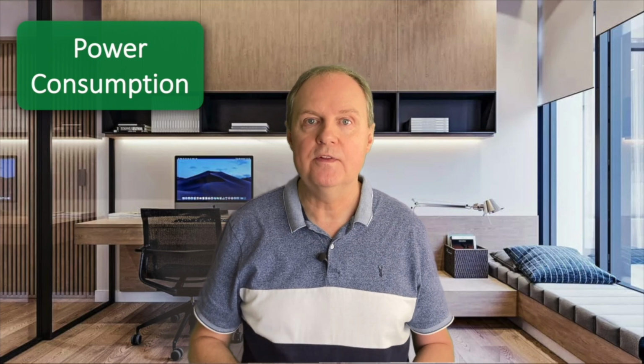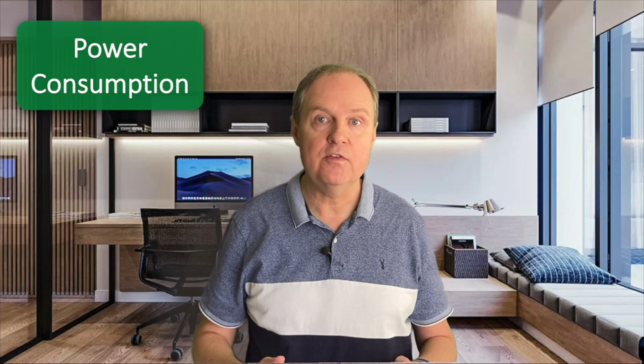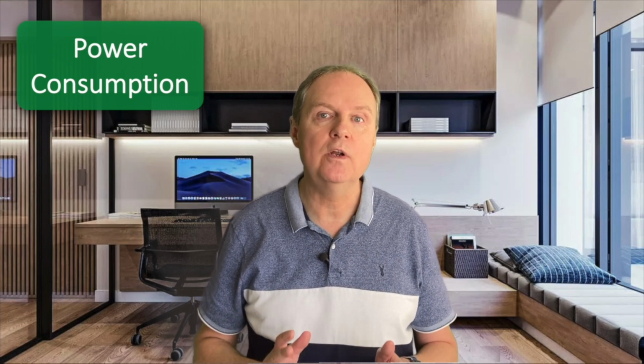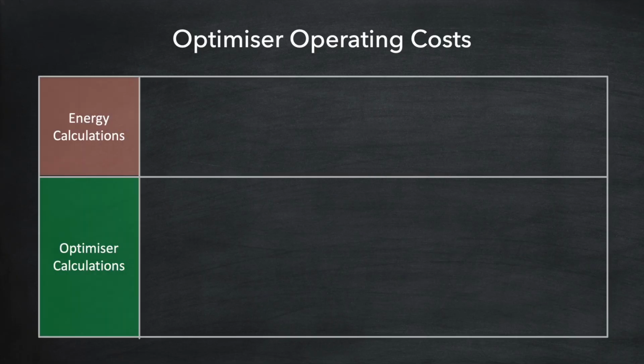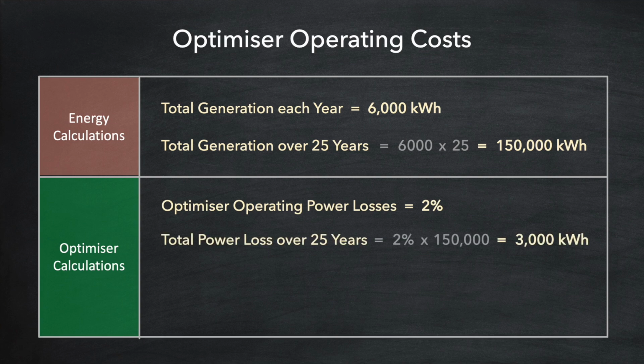real headache otherwise. The thing about optimizers is that they consume power all the time, even if they're not increasing the generation for large parts of the day. I've heard reports that optimizers consume around 1 to 2% of the total power your panels can generate. Assuming our solar array produces 6,000 kilowatt hours every year, over 25 years that's a whopping 150,000 kilowatt hours. Let's assume the optimizers on the array consume 2% of that power. This works out to be 3,000 kilowatt hours over the 25 years.